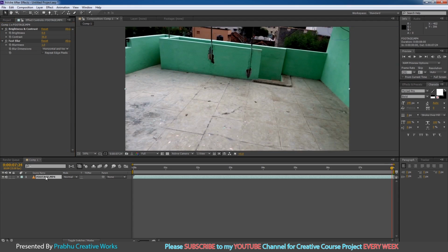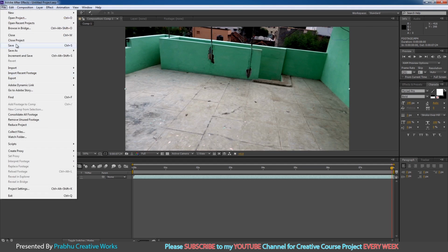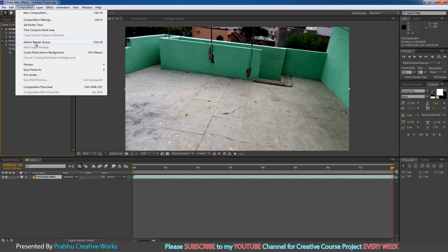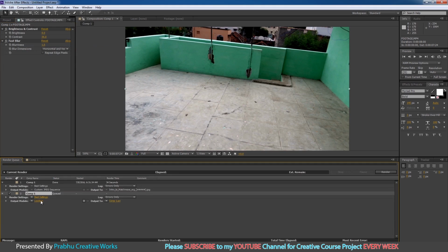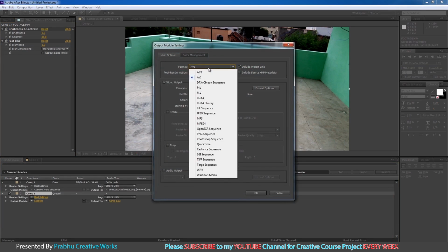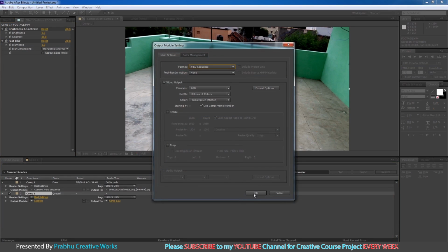Don't worry about this footage, it's only for our Boujou tracking purpose. In the final we will use our original footage. So now I want to convert this as color footage. Go to composition and choose add to render queue. Click this lossless, choose JPEG sequence and click OK.